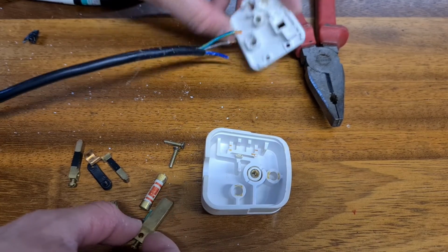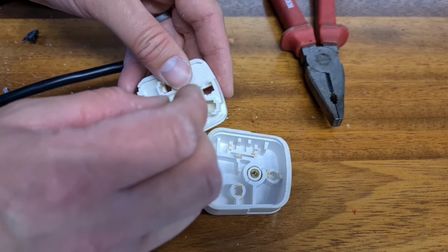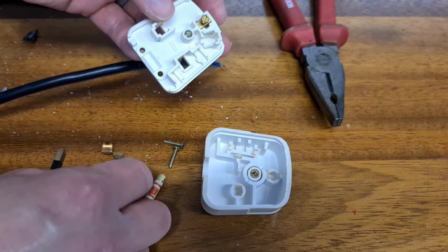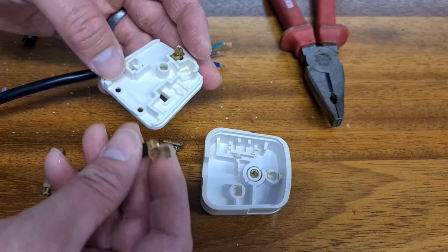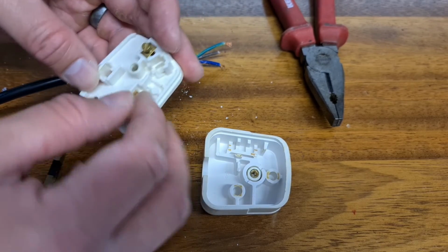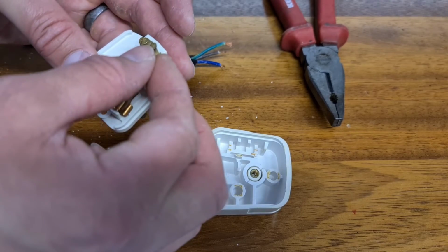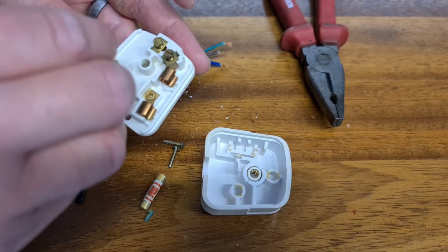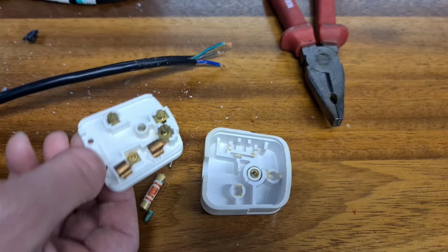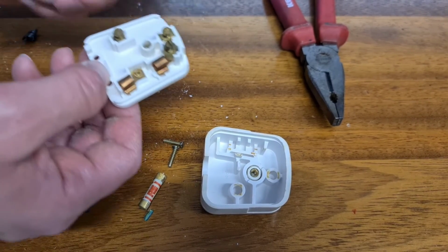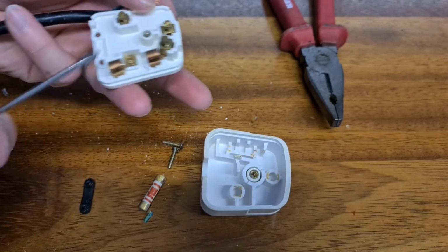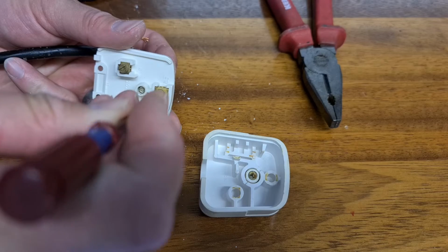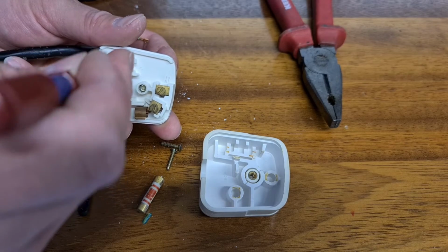So the next stage, I've got to put the plug back together. I'm going to put the earth pin in, and that's the only one that looks like that. Now I've got 2 cables here. The one with the small holder for the fuse is the live pin. There's the other end of that, which goes in just there, and then the neutral pin. Now this is the bit that's quite tricky to do and people really struggle with it. I recommend at this stage that you bring the actual pins all the way out without falling out.